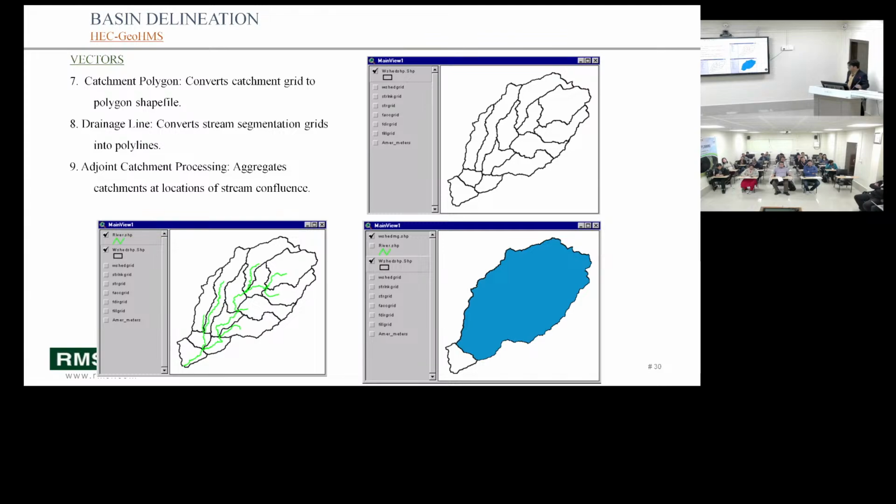Each subcatchment has one river file here. Let's say there are 10, 12 subcatchments. Now, as I mentioned yesterday, the hydrological characteristics vary in your basin, and you may want to make 20 subcatchments. You have information available with you, like land use, land cover change, and rainfall variation, whatever details you have. So the various hydrological characteristics of the basin are available with you.